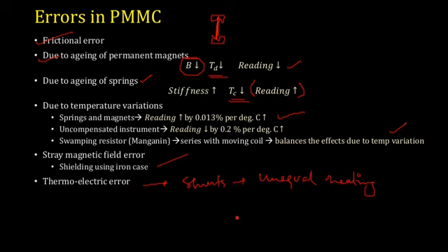Because of these temperature variations, some voltage will be produced due to the Peltier effect. This can again be minimized by connecting the shunt using some particular materials. These are very small errors which are generally neglected. Still we have such an error available in the system.